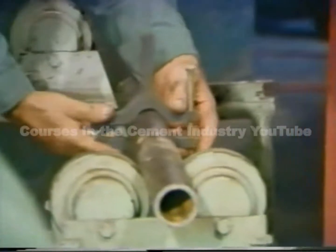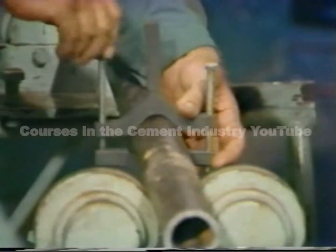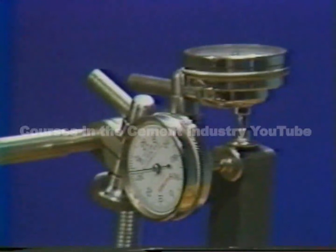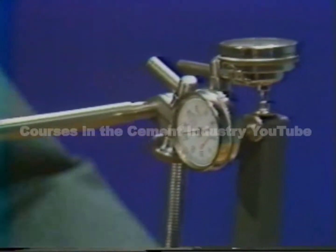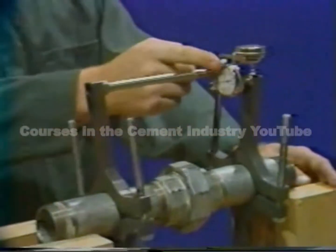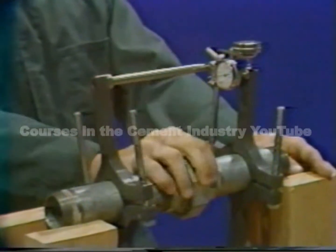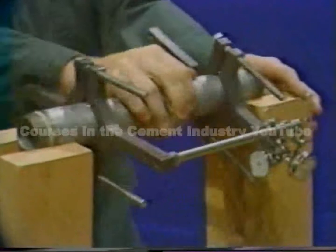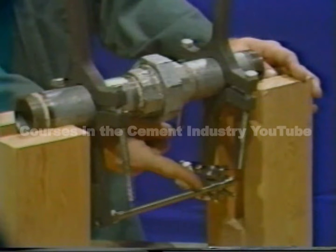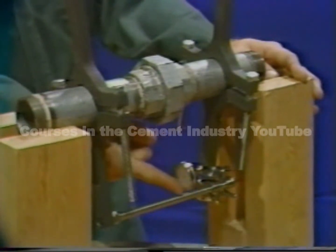Now, while he's installing the post, let's review. Dial indicators give accurate indications of misalignment. When properly mounted against an alignment post, two dials can be used to show parallel and angular misalignment. The rod attached to the bracket will sag slightly due to the weight of the dials. This sag must be determined so it can be compensated for in the alignment readings.